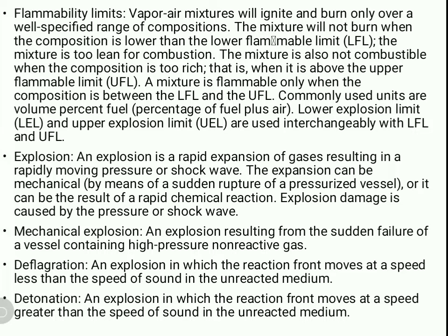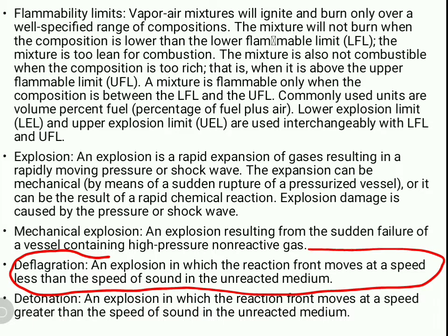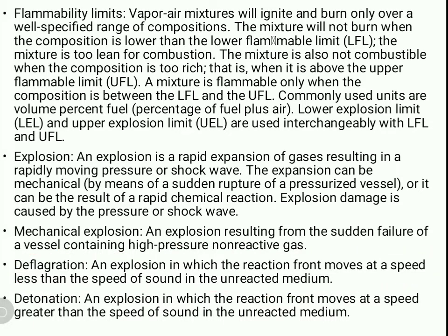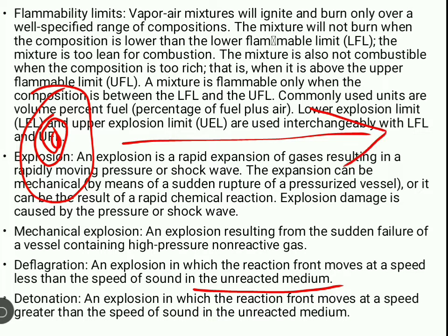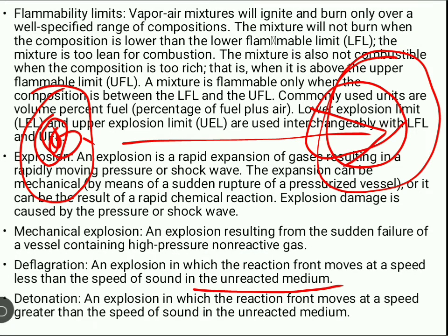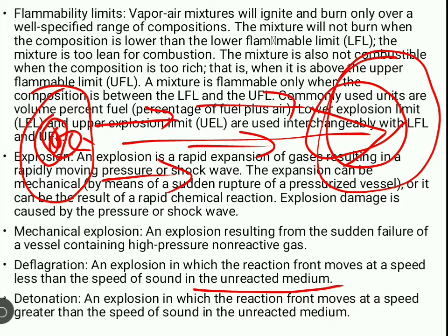Now another type of explosion is the deflagration type. The very important thing is that it is an explosion in which the reaction front moves, that is, the pressure waves created move at a speed less than the speed of sound in the unreacted medium. What is that unreacted medium? Suppose the explosion occurred at this point; this is the reactive medium, and everything other than that is the unreacted medium. Whatever explosion takes place here will create pressure waves and move towards the unreacted medium.